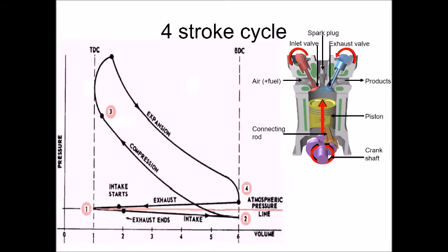Let's start at a logical place. So start at 1, there's our intake. 2, we start to compress. 3, we get some combustion. Over past top dead center, right to the highest point of pressure, back down we come, expansion. 4, then exhaust starts. That's me stepping through it quickly. Now let's go through it in some much more elegant detail.